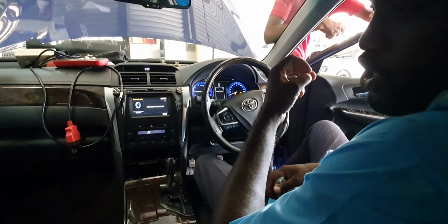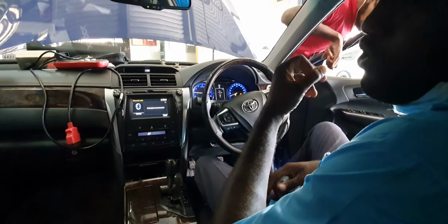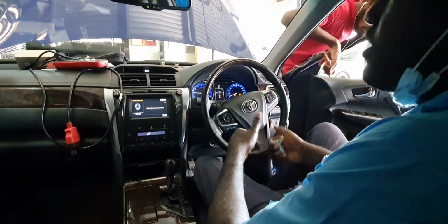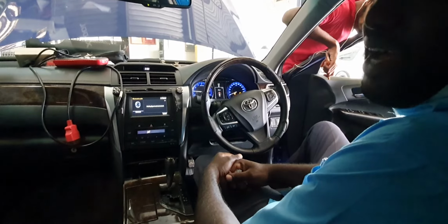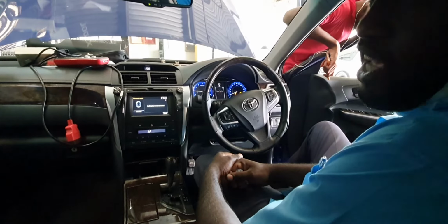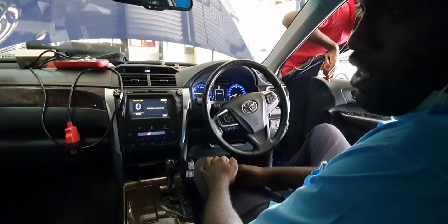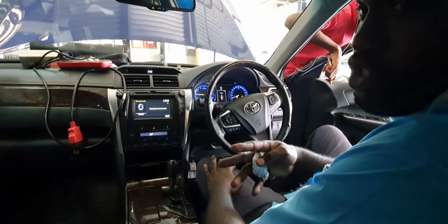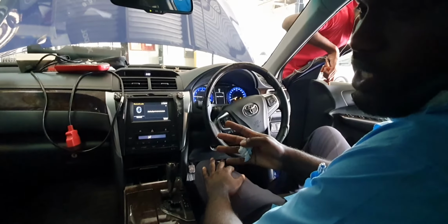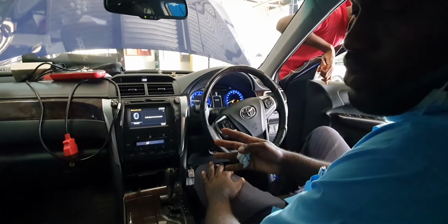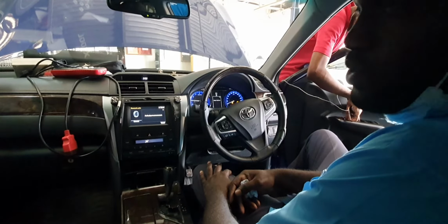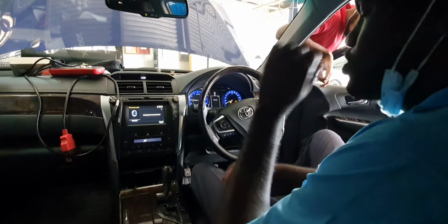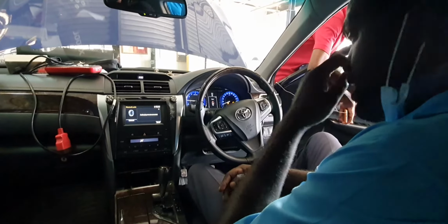Reason being, you don't know if a person has done a conversion on the vehicle, and when you lift up the bonnet, you will see all types of wire underneath. If you see all types of wire underneath the vehicle, don't use a scan tool on it, because it might destroy your tool. A good tool can cost anywhere from probably 200 US to even 2,000 US dollars, and you destroy your tool. So first, just do a basic visual inspection. Alright.